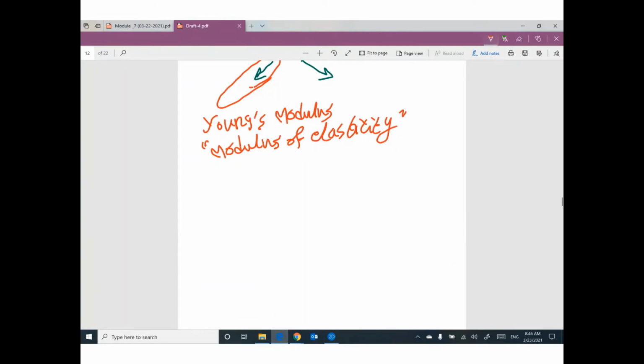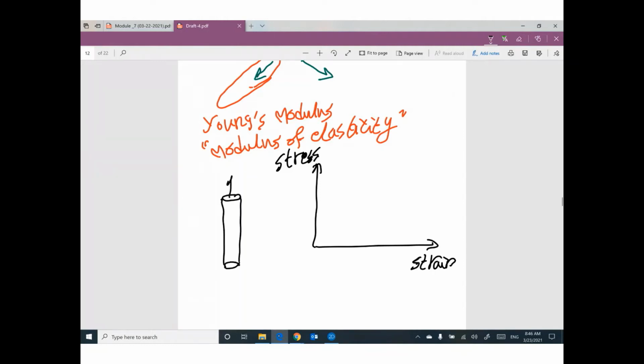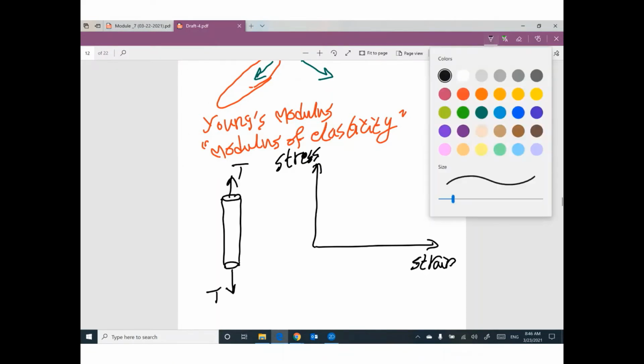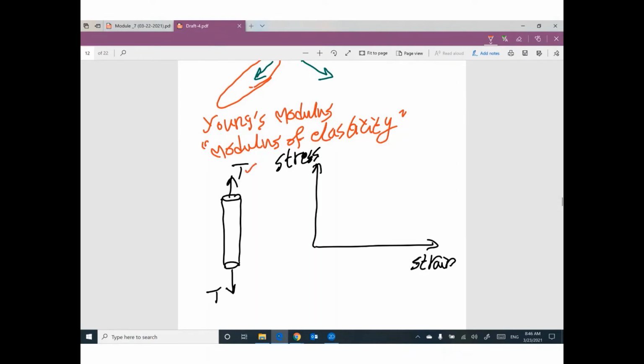Okay. We have something called a stress-strain diagram for steel. For example, if you have a piece of steel or rod of steel and you apply a tension test, if you apply a force, we can expect elongation. This elongation and this force can be converted to a stress-strain curve, and your curve looks like this.